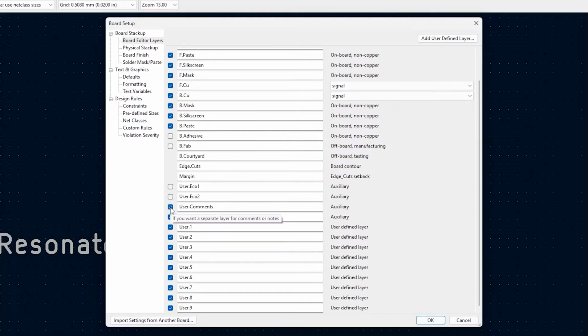We can also turn off the drawing and comments, which are generally used for user reference and have nothing much to do with the PCB. Finally, we can also turn off all the user layers. They are user-defined layers where we can add special features to the PCB and also convey some information to the fabrication plant or to some other design engineer.